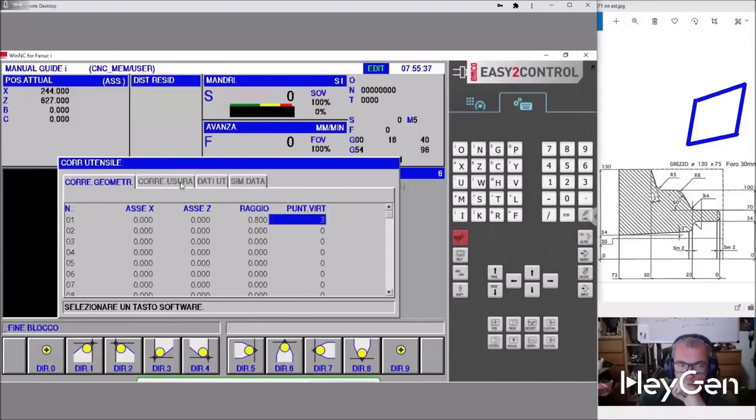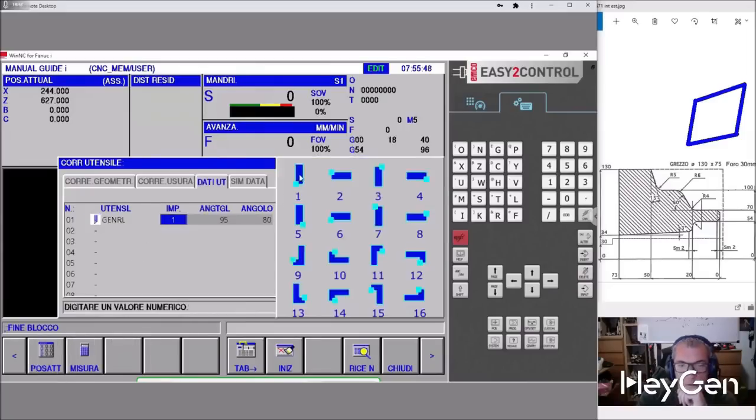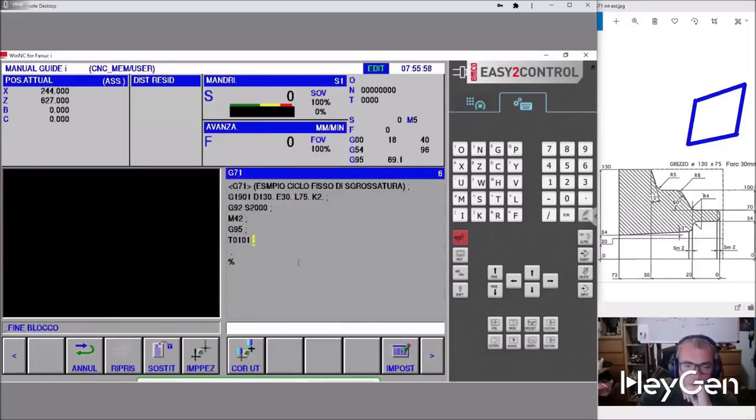The tool setup is crucial for precision and accuracy in machining operations. The rhomboid shape is chosen for its geometric properties, allowing optimal tool engagement. The virtual point is a calculated reference, vital for determining the tool's path. In manual mode, the operator controls tool movements. In ISO mode, the machine follows instructions. G42 and G41 codes are essential for compensating the tool radius.